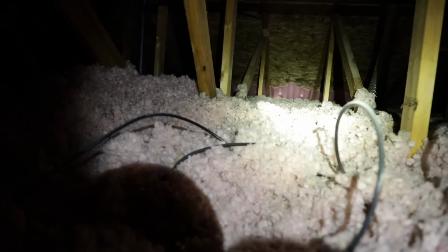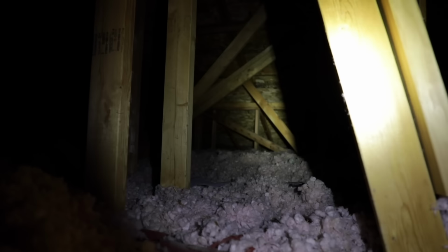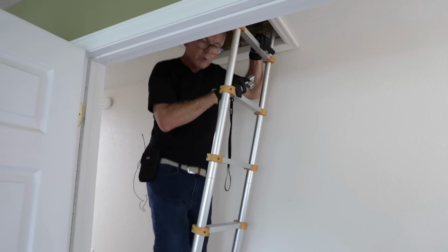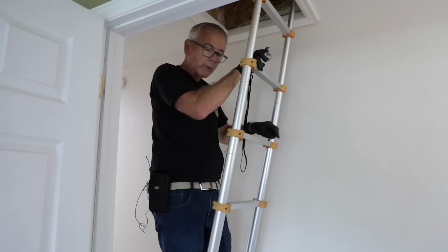Okay, what we have up here is we've got approximately 16 inches of blown-in fiberglass insulation. And it looks to be covered really well. I don't see any uncovered spaces, which could develop some cold spots in the finished area below. I'm going to take a couple of reference photos while I'm up here. So everything up here looks really good. It's covered well, and it seems to be throughout the surface of the attic space, so I don't see any problems. We're going to move on to our unfinished area in the basement.